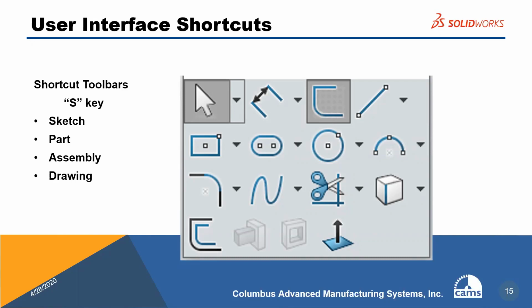And so SolidWorks has come up with this Flyout toolbar that brings this toolbar out at the stroke of the letter S key on your keyboard, wherever your cursor is. So you can populate this to whatever you want. And the way you do that is you put your cursor in this window, you right click, and you'll see the word customize. And when the word customize comes out, you'll be able to add by drag and drop any other tool that you want to bring into here.